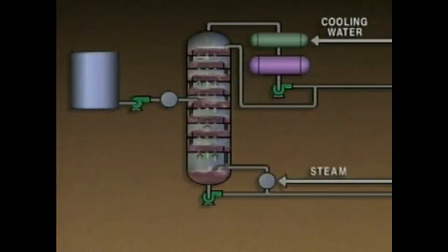In order to maintain the proper temperature gradient, temperatures at critical points in the system must be controlled. Temperatures in a distillation system are typically controlled in three ways. One way is to control the temperature of the feed mixture by using a preheater. This regulates the temperature at the feed point. At the bottom of the tower, temperature is controlled by the amount of heat that is added by the reboiler. This added heat is referred to as boil-up.